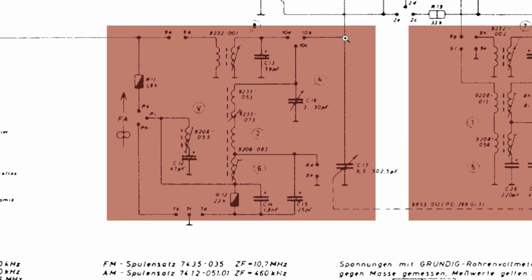go to this point over here, which is connected to one half of the variable condenser. And when we tune this condenser, it tunes to the frequency that we want to listen to and sends that up into the mixer circuit. Now, this is the last part of the entire tank circuit that this section here sets up for us. So this condenser is the common denominator of these pre-selections, and it's one condenser that works for all three bands and tunes that band to the particular frequency that we're looking for.